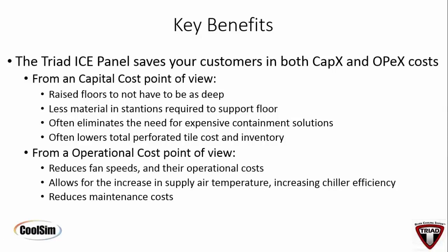That's a big deal. Remember, fan law is cubic, so every time you move it down a few RPMs, you're getting a cubic relationship in power savings associated with that fan. So that's why VFDs are very popular. So this will work very nicely with a VFD system.